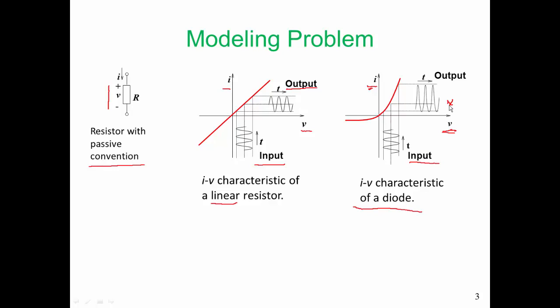Now if we applied a signal to the input that consisted of two sinusoids, the output will consist of a signal which consists of those original two discrete tones plus the harmonics of those tones plus the intermodulation frequencies of those two tones. That is, all integer sum and difference frequencies of those two tones.